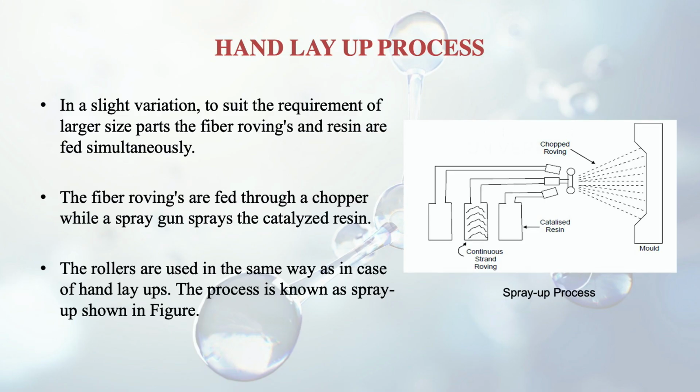The rollers are used in the same way as in case of hand layups. Your function for the roller is same as in case of the hand layup, that is, removes the entrapped air and also spreads the resin evenly. So this is the process of spray.